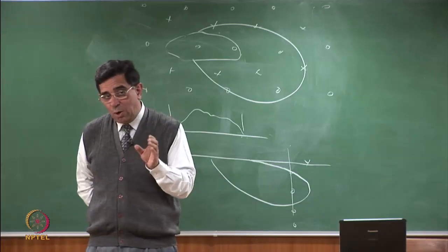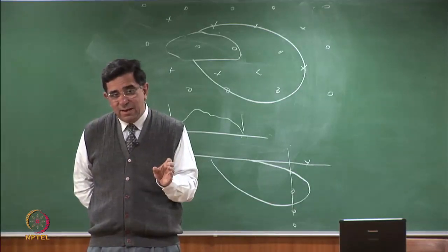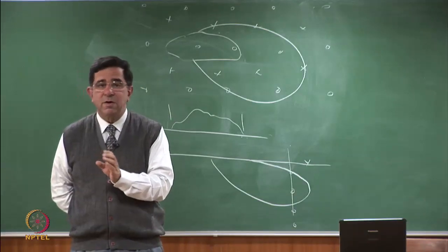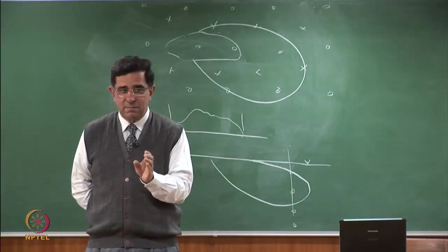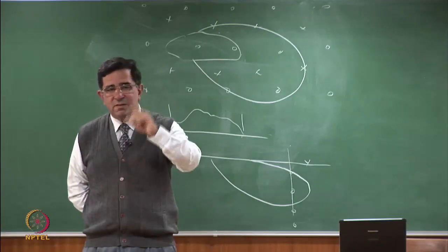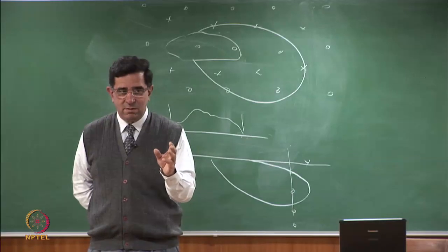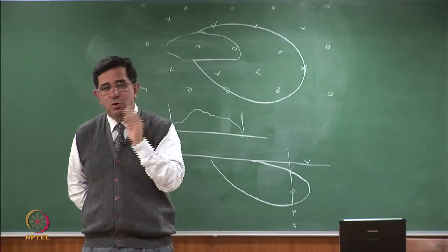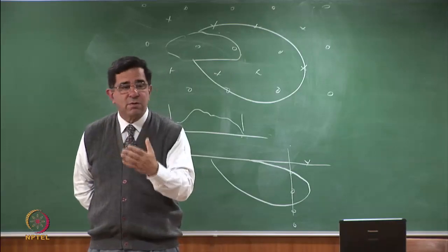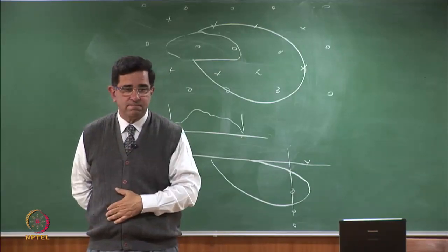But I do wish that you read up on how a normal well is so different from a monitoring well or a monitoring well cluster, and how screen length is not important in a normal well, where the sealing is done is not important in a normal well, and how it is so important in a groundwater monitoring program, quality monitoring program.